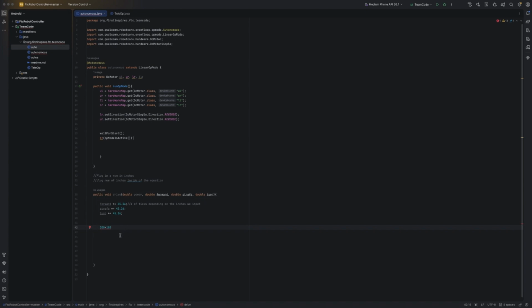If we don't reset our encoder to 0, it's only gonna move a certain amount. It's not gonna move the actual amount, because it's already at one position. So we have to reset the position. If we tell it to reset to 0, then it starts at position 0 now. Think of ticks like the position inside of a motor. It starts at position 0.